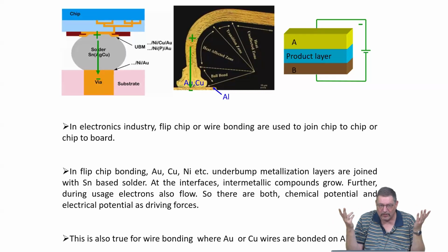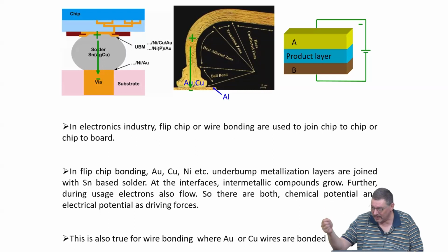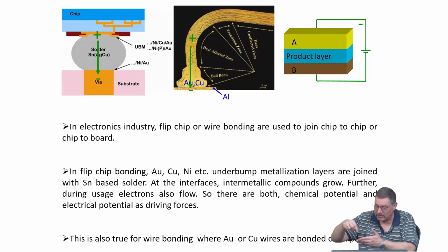So diffusion bonding, the term is very well known. It's also very important to do quick bonding on a chip, for example, of the gold wires. It's typically done not by soldering or anything like that, but by this wire bonding. So you tip the wire and the current flows as soon as the interaction distance is small enough, and then automatically it's heated up in the right position and it will do the bonding.